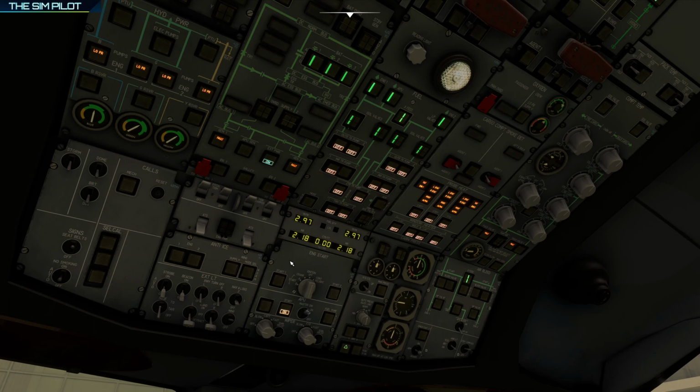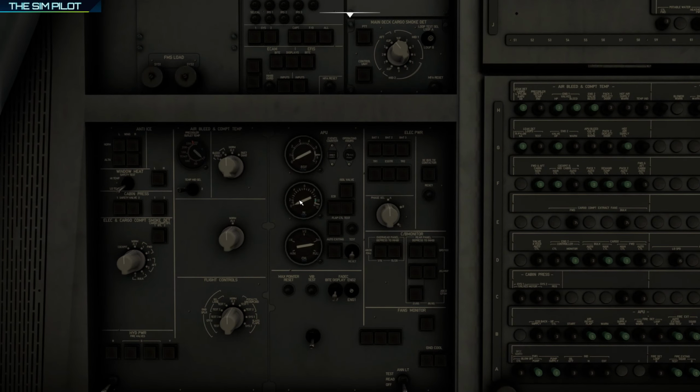And remember the panel that I showed you, this is gonna take some time. The flap will open and then APU will start spooling up, and the start switch will show acceleration, or accelerating, on the switch in green. But if we go to the back, we should see the gauges moving as the APU starts spooling up.